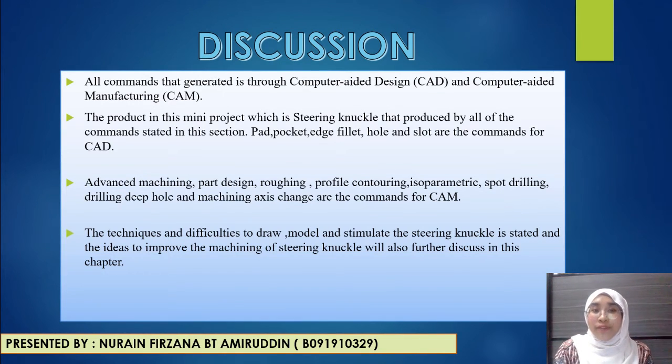Assalamualaikum, my name is Nurain Firzana. I will present the discussion of our project. All commands were generated through computer-aided design and computer-aided manufacturing. The product in this mini project, which is a steering knuckle, was produced by all of the commands stated in these sections: pad, pocket, edge fillet, hole, and slots are the commands for the CAD, while for the CAM they are advanced machining, part design, roughing, profile contouring, isoparametric, spot drilling, then drilling deep hole, and also machining axis change.